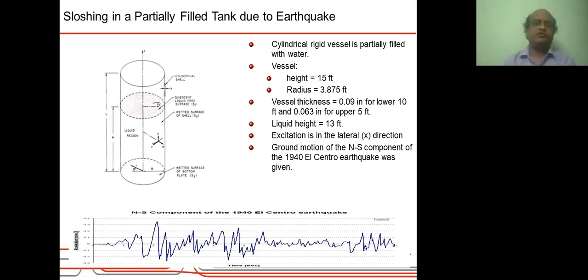the spectrum of the earthquake is shown at the bottom, which gives the acceleration of the ground with time. You can see it is very chaotic. When it is subjected to this, the tank on the ground also oscillates. So that will introduce a sloshing of the fluid, and with the sloshing, the fluid levels will be changing. So that will be changing the hydrostatic pressure forces on the structure. So that will cause a pressure imbalance there, and the structure may have relative deformations.